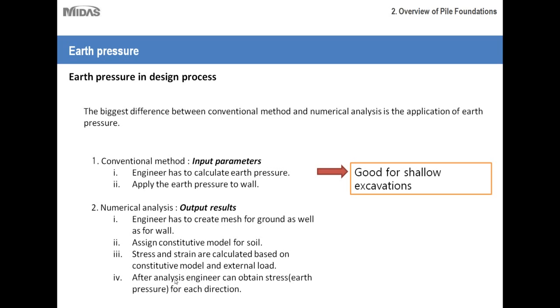Okay, and then after the analysis, the engineer can obtain stress, also known as earth pressure, for each direction. Once again, this is something that the program takes care of for you. And then this is a must-use for deep excavation. When you get to larger scale projects, for example an excavation for a high-rise building, that's very complex. There are going to be multiple construction stages, and the support or bracing systems will be much larger in scale and much more complex. As you can imagine, the conventional method would not be realistic for that, because there are so many variables that the conventional method can't take into account, that numerical analysis, however, can.